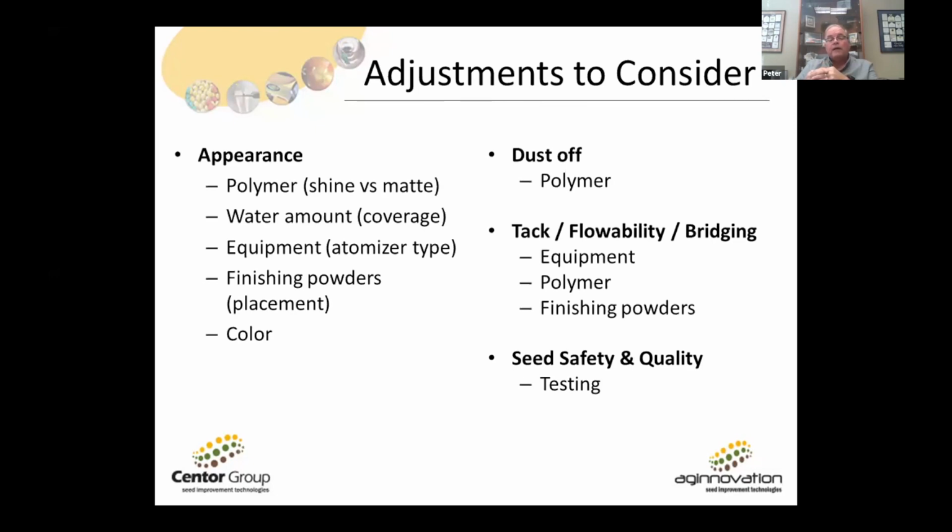It's just a fact of life that we don't clean the atomizer as much as we ought to. With the basket types, over time we tend to clog the holes in the basket, and we don't get good movement of liquids off that basket into the seed mass because the holes are plugged. Using a flat disc with a slight edge allows us to have immediate success of getting liquids onto seed, and very minimal issues on cleaning.